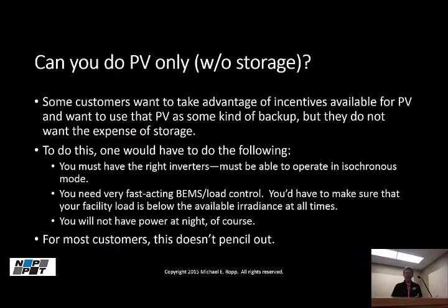Can you do PV without storage? If you're talking to your local Target store, they've got a 500 kilowatt array on the roof. They've got no backup generation, no storage. They want to say, hey, during a blackout, can I use that as my backup power source? The answer is, well, technically yes, but it's a very difficult thing to do. You've got to have the right inverter again, but you have to have really fast load shedding because I've got to get the load below the generation. And of course, the generation's changing.